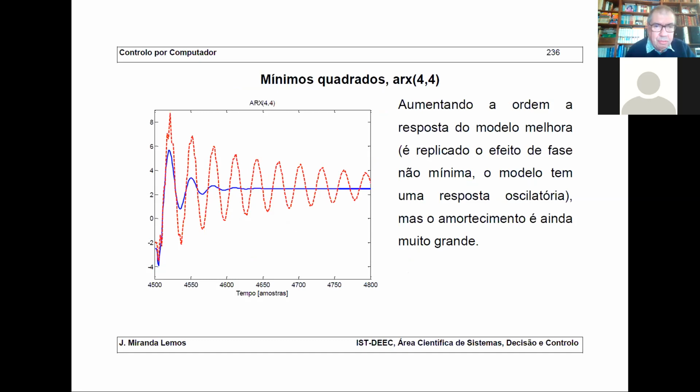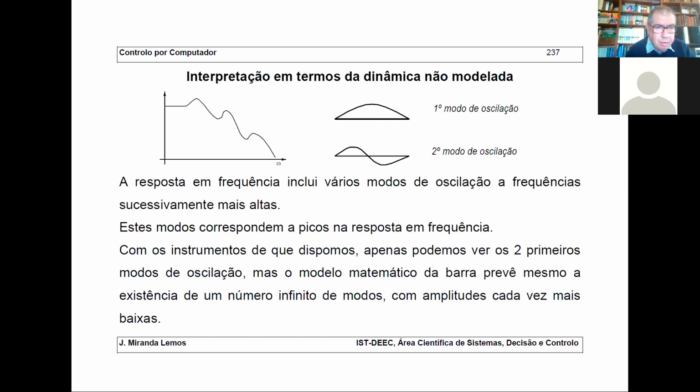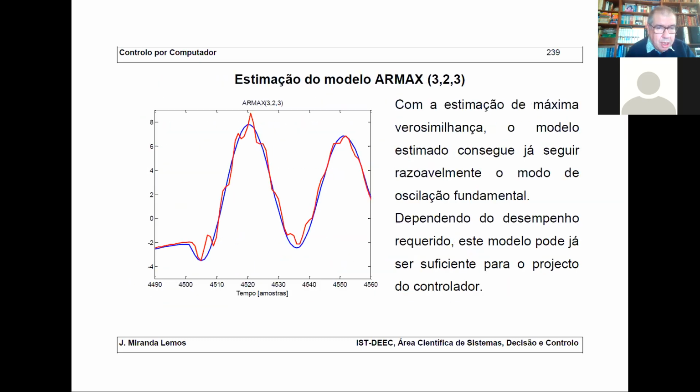Let's see what happens if we use maximum likelihood. I will go back to those two slides. And let's go to the original 3 poles and 1 zero, 2 coefficients, because we have B0 plus z^-1 B1, so that's one. And NB equal to 2, that's 1 zero. And then I have NC equal to NA. So I'm estimating the correlated noise.